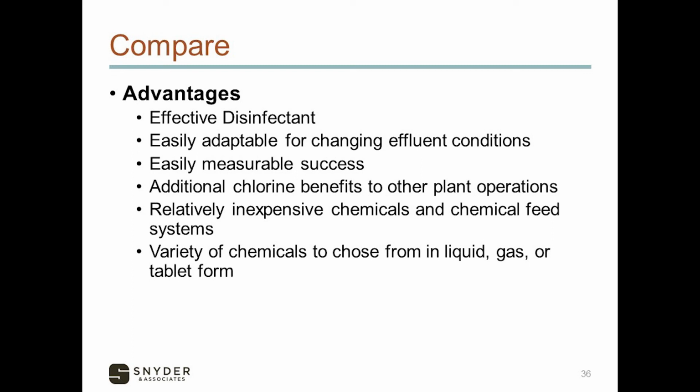In addition, the advantage from chlorine, we said, is relatively inexpensive. Well, sort of. The cost of the chlorine is inexpensive. The cost of the equipment is inexpensive. The cost of the concrete tank is quite expensive. You have multiple options too with chlorine. You can get calcium hypochlorite, sodium hypochlorite, chlorine gas, on and on and on.